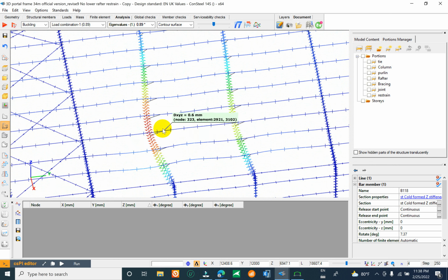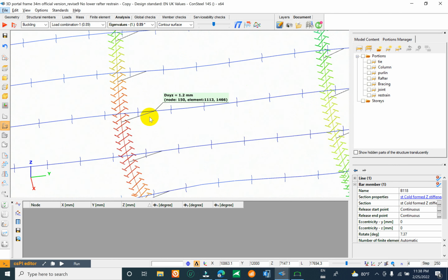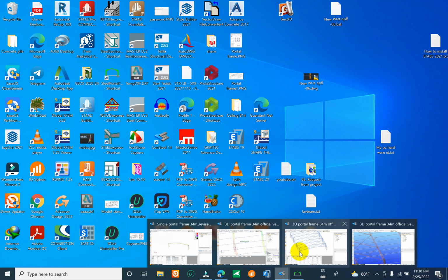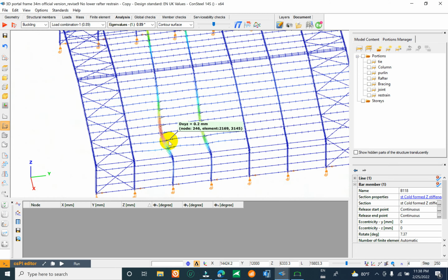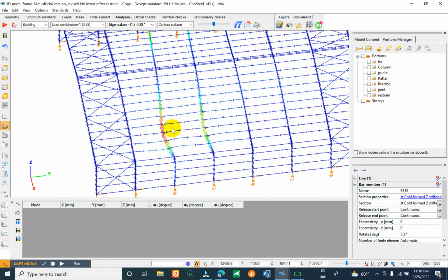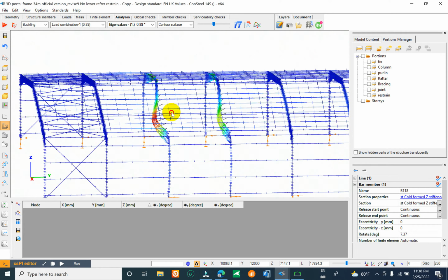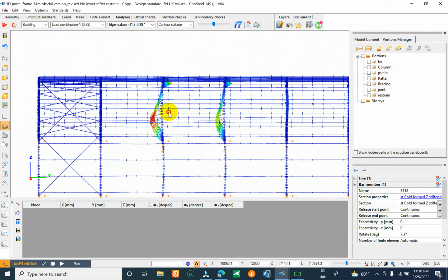So you have to add the pressing. I call it the pressing from the bottom to the top of the purlin. It is very important. Okay, very important. So you see the phenomenon that occurs from the applied load. You can see here the out of plane.